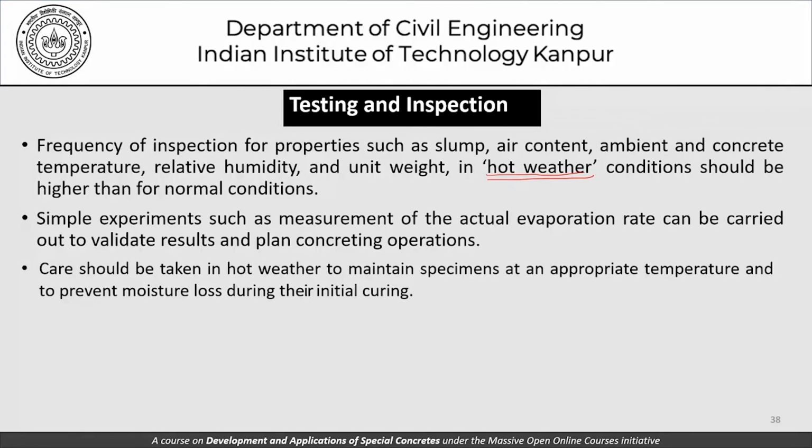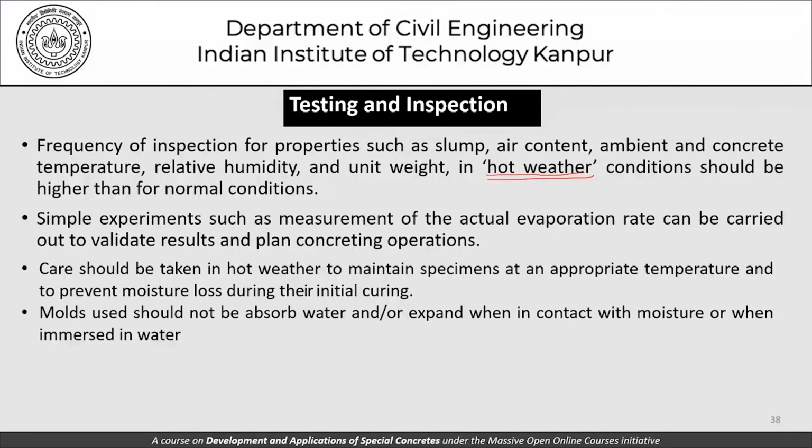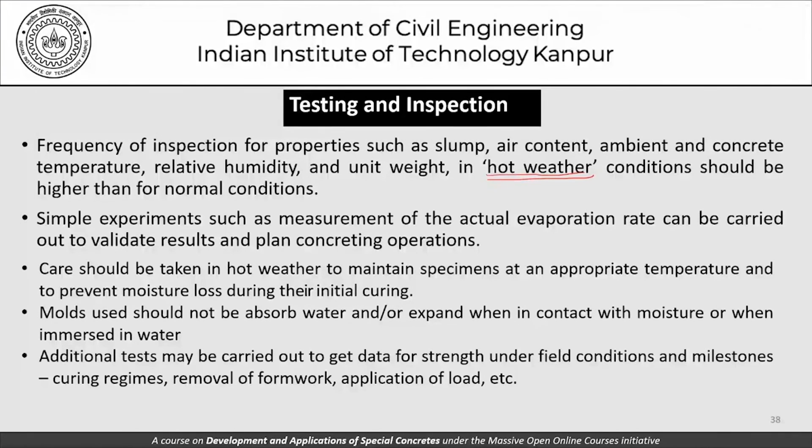Care should be taken in hot weather to maintain specimens at an appropriate temperature and to prevent moisture loss during their initial curing. Molds used should not absorb water or expand when in contact with moisture or when immersed in water, and additional tests may be carried out to get data for strength under field conditions and milestones in terms of curing regimes, removal of formwork, application of fluid, etc.